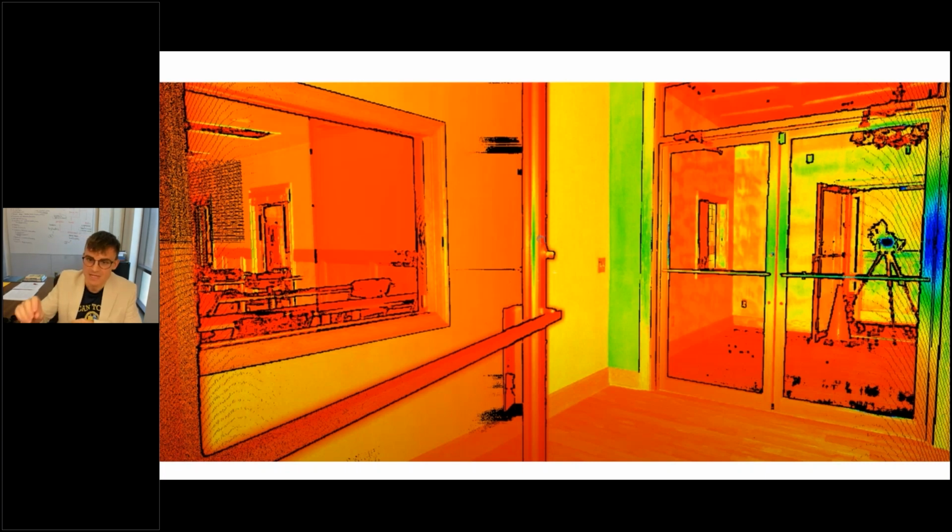For example, when scanning through internal glazing, like we see on the left side here, these measurements are a problem because they're slightly inaccurate due to refraction, but also closely overlapping good data. We see the two-toned point cloud where the good and bad data are overlapping. This will cause problems during registration, so this type of noise needs to be cleaned out,